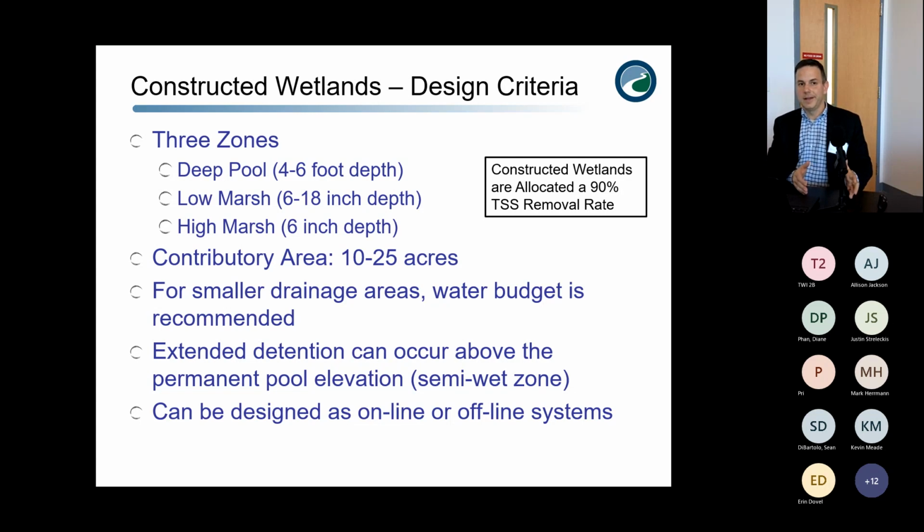We've seen that a lot in the designs that we do, where maybe only the 1.25 inch water quality storm gets diverted with a weir into this wetland, but then if you get a big flush of rain, it goes over the weir and just moves downstream, so you don't get that damage to the wetland that would occur from a big inflow of runoff.